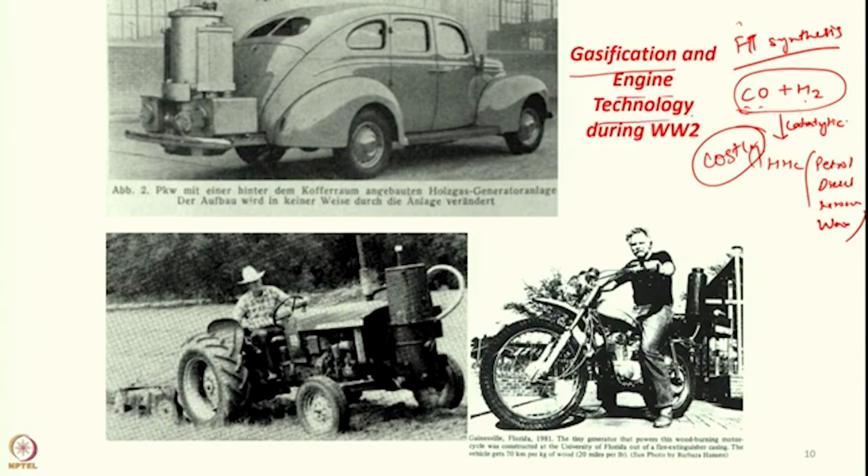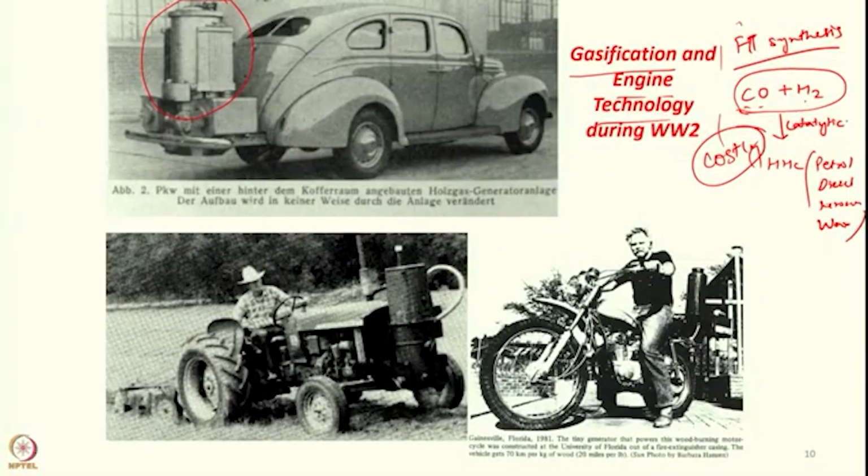So, what they did is, rather than looking for coal or something, because this process of FT synthesis is costly, not the gasification process, and biomass is also available. So, rather than coal gasification, they designed such reactors, which were biomass gasifiers producing gas. It was giving you carbon monoxide, hydrogen and methane, and this was going into the ICE engine. So, they developed the technology which can fuel the conventional petrol or diesel engine.